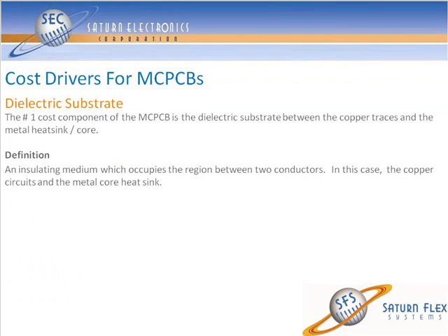First of all, these are typically high volume products, LED applications. Cost is a major, major concern. And your number one cost component of an LED board, which is your typical metal core single layer that we see the most volume of, is that tiny thin little piece of dielectric in between your copper circuitry and your metal base. That deserves to have focus put on it. Essentially, it's your insulator for shorting out to your base, and it's your conduit for transferring heat.